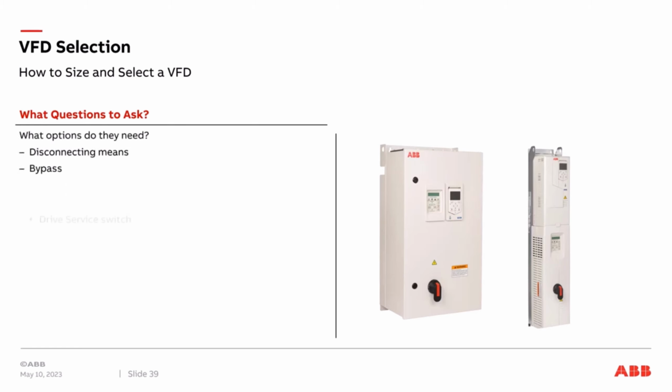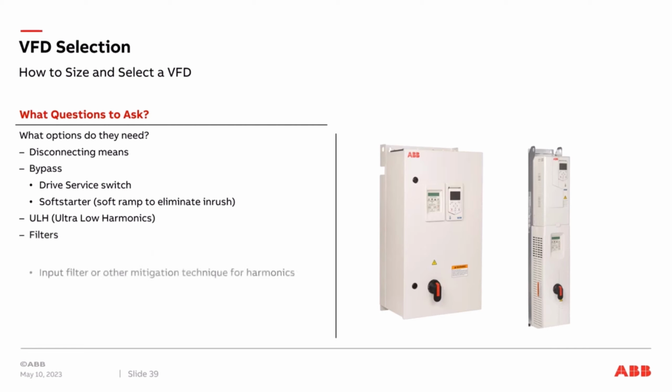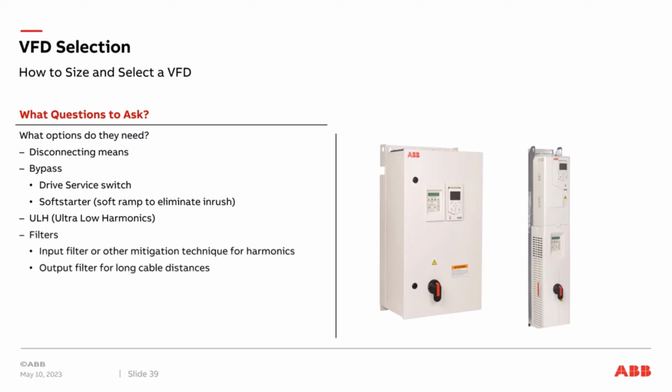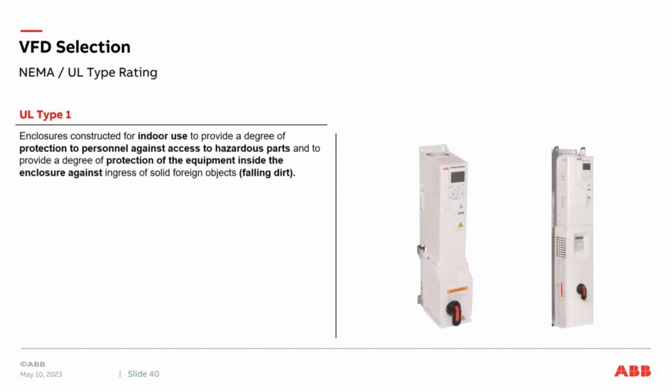Disconnect means, bypass, drive service switch, soft starters, which is a soft ramp to eliminate inrush, ultra-low harmonic drives, input filters and other mitigation techniques to reduce harmonics, output filters for long cable lengths, option cards for communication protocols, and extra relay outputs. A UL Type 1.